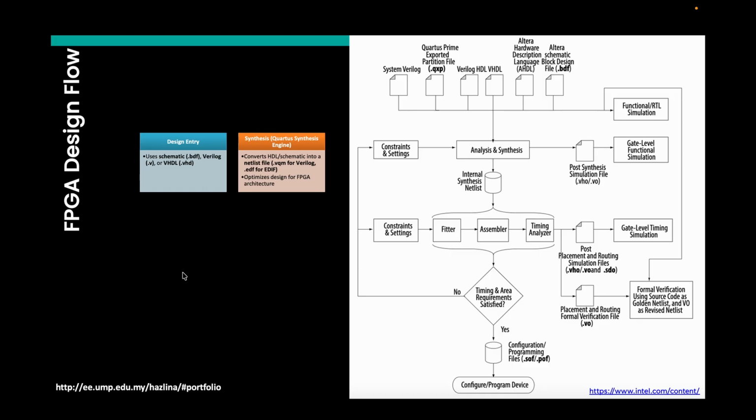Now we move into register transfer level, RTL, where we write the system's logic using a hardware description language like Verilog or VHDL. For example, if we want to control an LED in the Pico satellite onboard controller, we write Verilog modules that turn the LED on or off based on sensor input. This stage represents the actual coding of the hardware design.